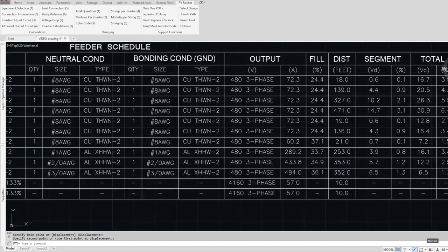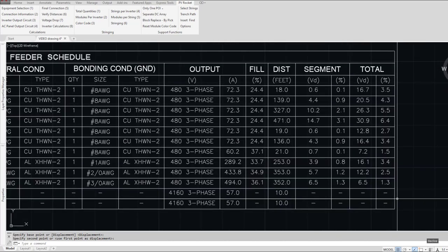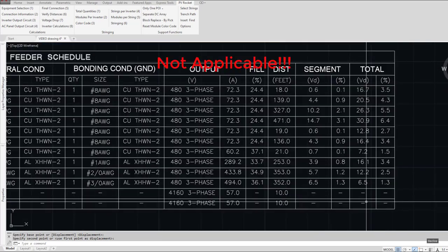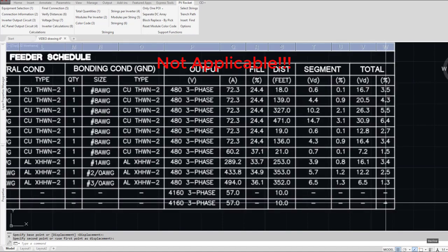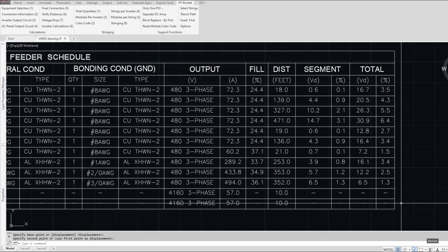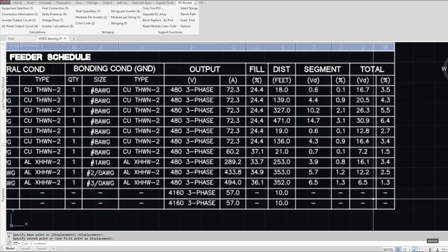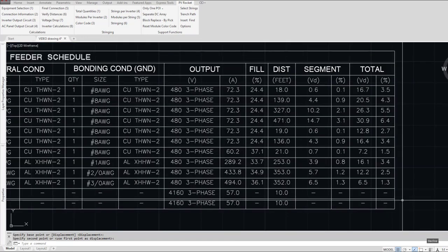The voltage drop goes to, I almost said obsolete. Well, kind of. I guess that's kind of correct. I don't want to use the word negligible either. Just not relevant, because if it dropped, which it's not because it's only 57 amps, but if it did drop, there's taps on the transformer that you could change, I believe.